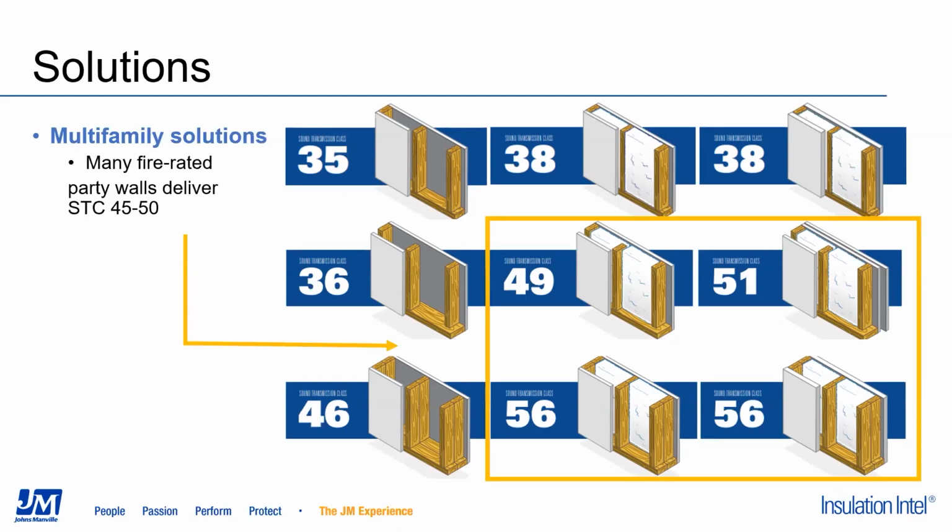So I just want to point out, you may be trying to shoot for code minimum IBC STC 50 performance. These four would be your best bet to get close to that, and they may work well where you have space available. So that would be good for your multifamily demising systems, or even single family walls where you're looking for higher performance, maybe with a home theater room.